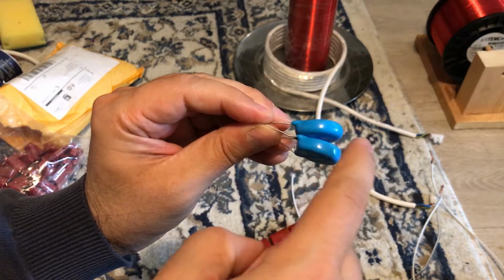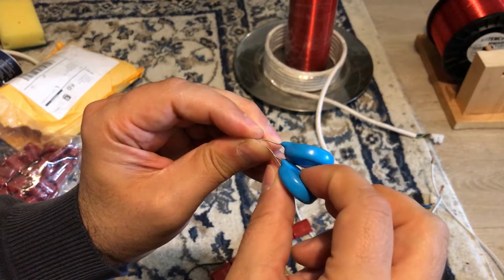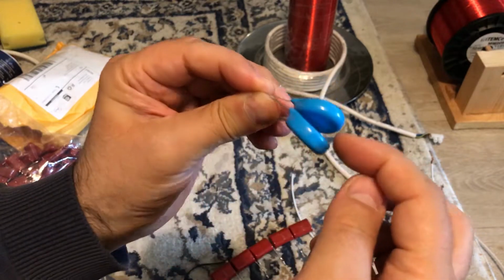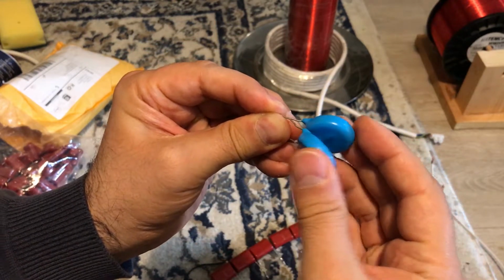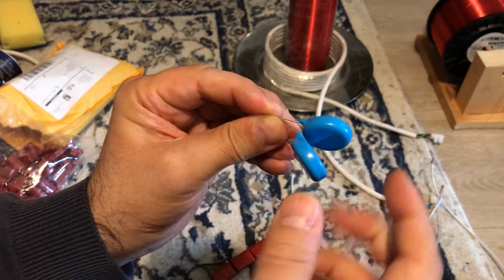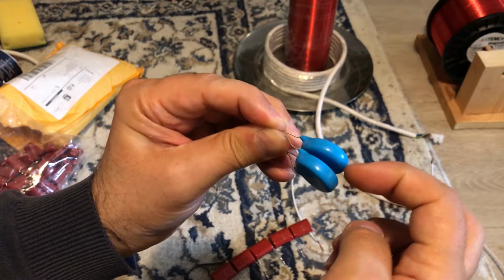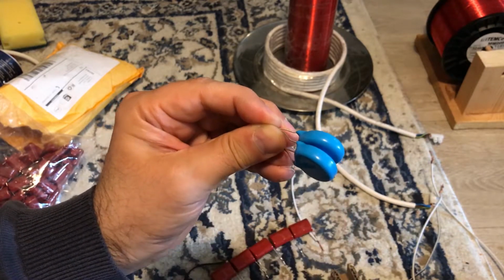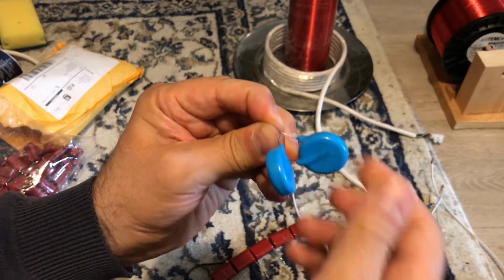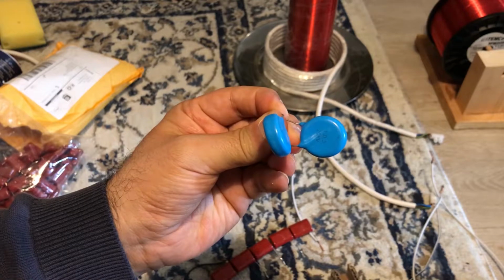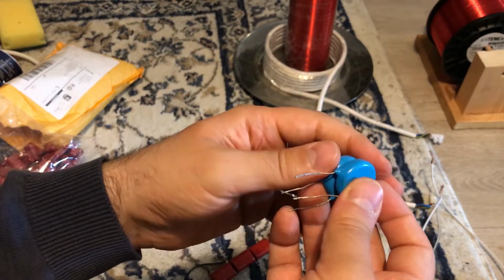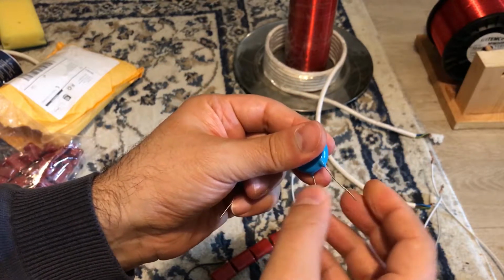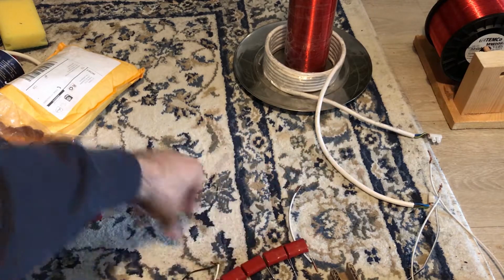Because this leg of the first capacitor is connected to this side, but the other capacitor leg, the other side, is also connected to this side of this capacitor. So basically this high voltage that we have between the terminals will also fall in between these two capacitors, which may cause breakdown through this region. So if you want to make them parallel, at least create some distance between them. But in general, I do not recommend using this blue capacitor. You're going to burn them. I have already burned these two. Use the red capacitors. Either this one, better would be this one.